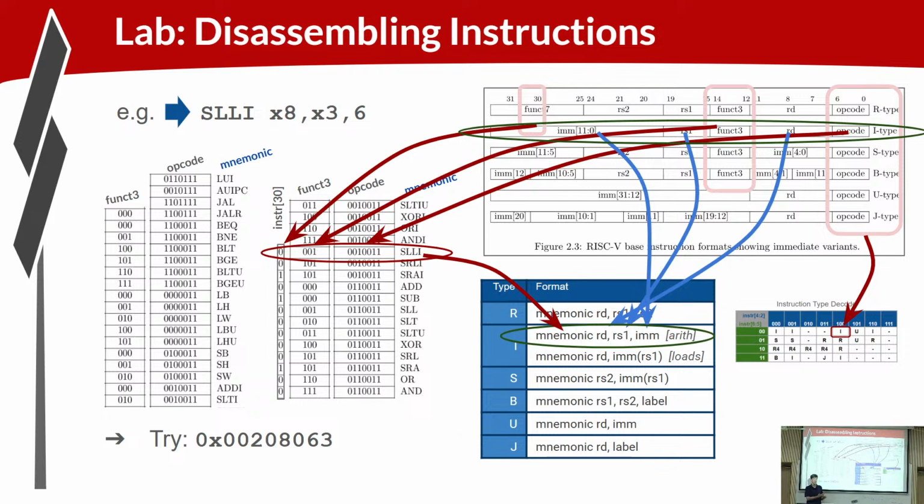There is an architectural extension for compressed instructions, which can be 16 bits. So if you have support for compressed instructions, you might need an additional bit. But we don't need the low order bit that's byte granular. We need a 16-bit granular offset, right? So there's no point in wasting a bit in here that's always going to be 0. So the B-type encoding does not include immediate bit 0. That's just implied to be 0.